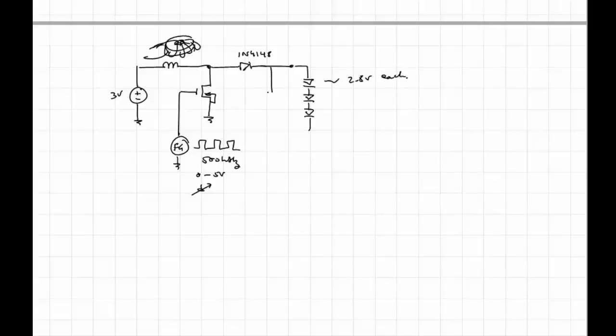I have a little capacitor here to provide some filtering. And lastly, we'll put in a little resistance to ground, because that will allow us to measure the current, and if we take this capacitor out, this voltage here will be equal to RS times ID.